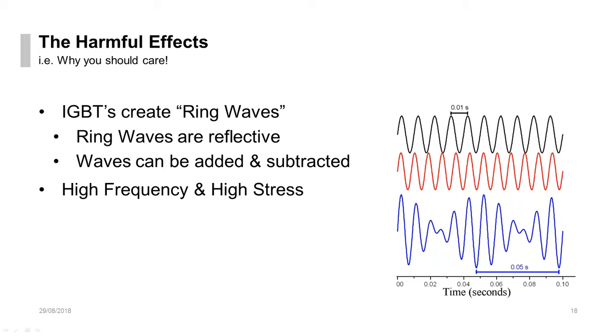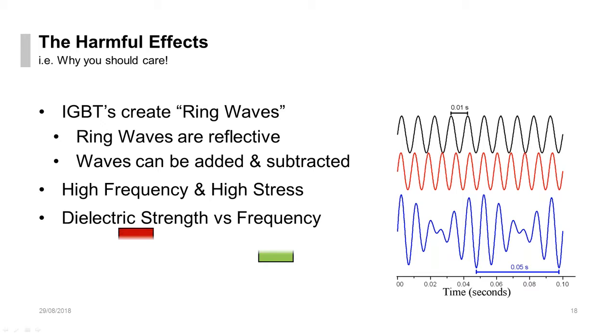Heat is one part of it, but you can also think of this as a hammering effect. Every time you have one of these spikes, it's actually beating on the insulation of your motor and your electrical system at large. It can also lead to mechanical problems, where you can have shaft breakages due to torque issues that are being created by this high frequency content.